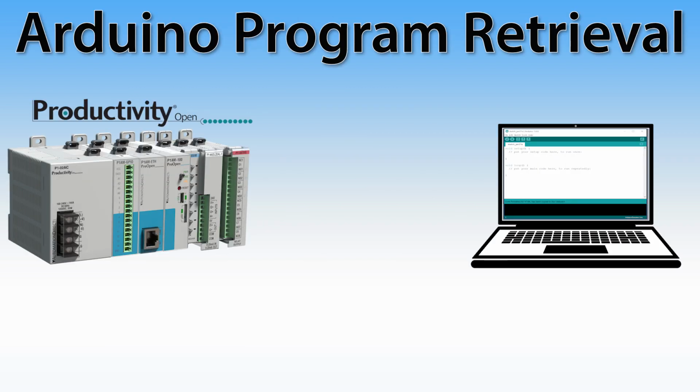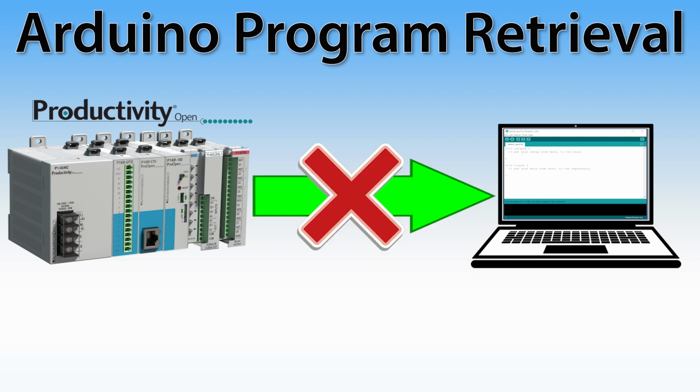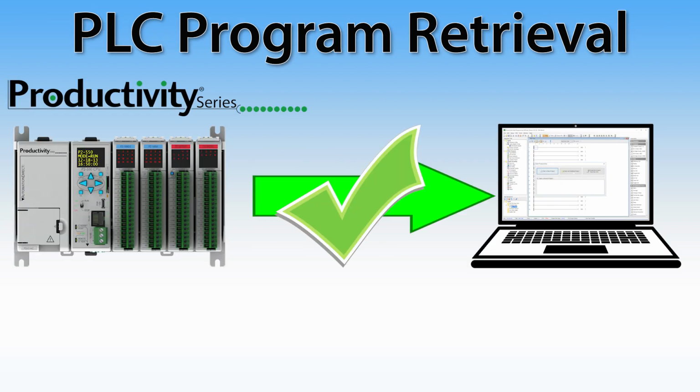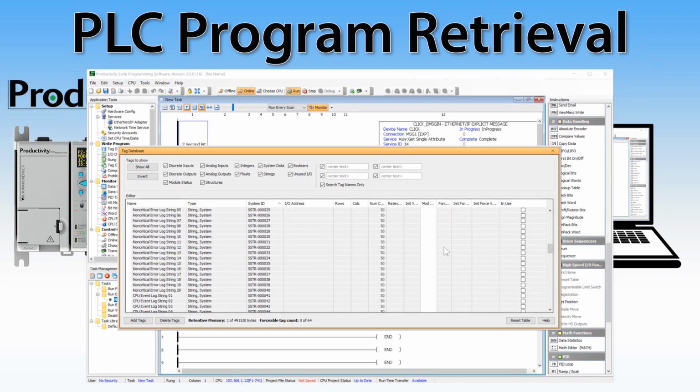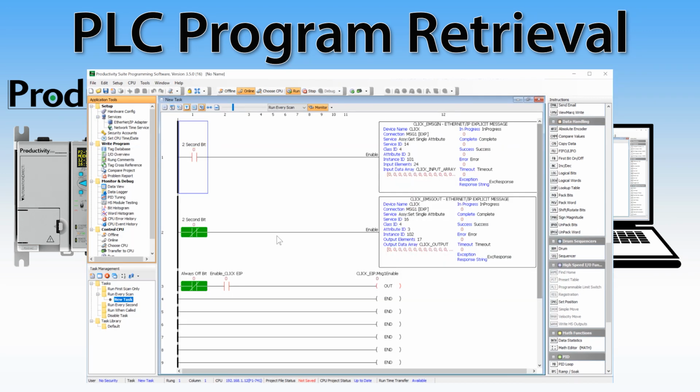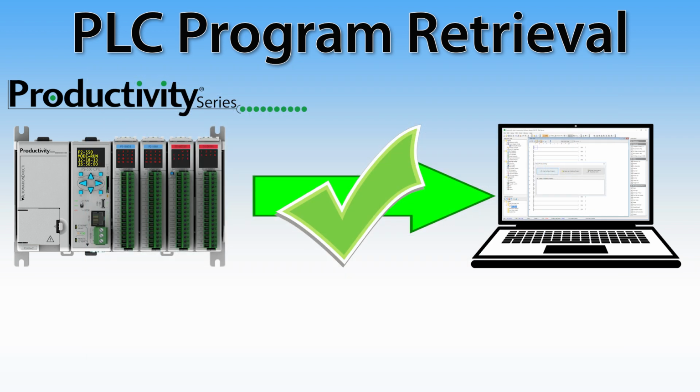First, and this is a big one for most typical PLC users, there is not a way to get connected to an Arduino microcontroller and download the current project that resides inside the Arduino. On Arduino, only the machine code for the processor is stored on the microcontroller. Whereas with most PLCs, the complete project is stored on the PLC, with comments, variable names, instructions, and you can even connect to the PLC, download the project, and then make edits or troubleshoot your code. This difference introduces a few challenges when using an Arduino.